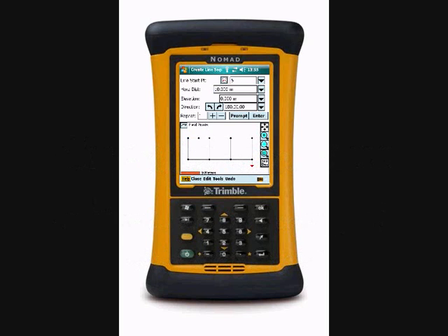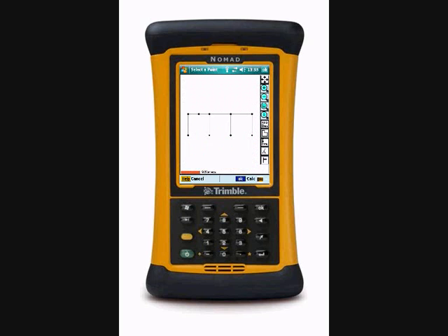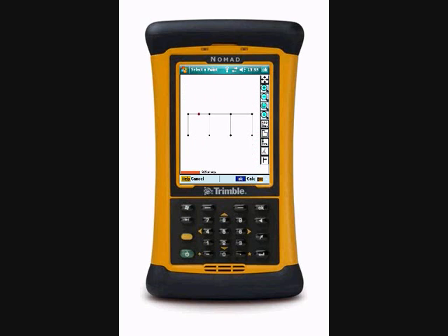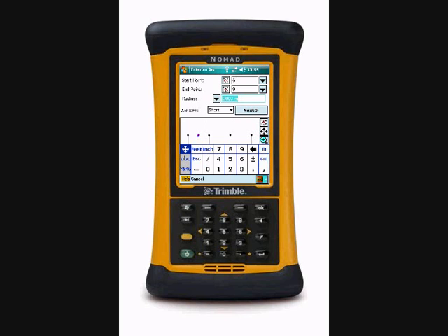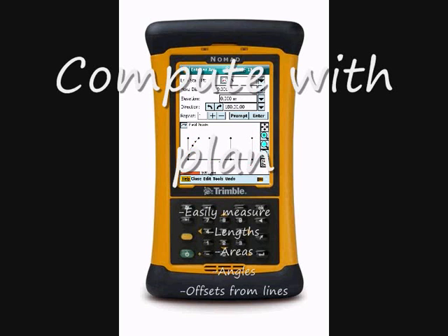There we go. Now, looking at inputting an arc, to do this is very simple. All we have to do is choose a start point there, the end point there, and key in the radius of the arc we want to describe. We'll get a preview. Now if we don't like that, we can simply flip it by pressing that button there, and we can enter subdivisions along that arc. It'll automatically calculate the points for the intersections, and we can also include a radius point.